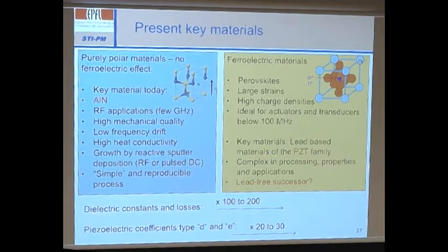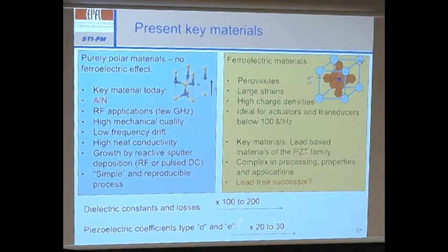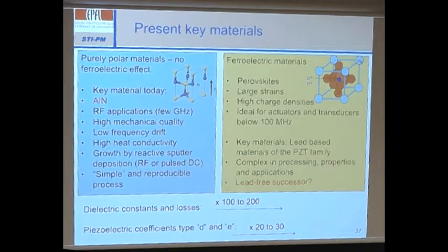You see also the properties change. The dielectric constant and losses increase by 100 to 200 when you go from left to right, and also the piezoelectric coefficients increase by 20 to 30 when you go from left to right. So this is justifying the existence of PZT. Anyhow, medical imaging you couldn't do without PZT. You need a very good contrast, a very strong material.